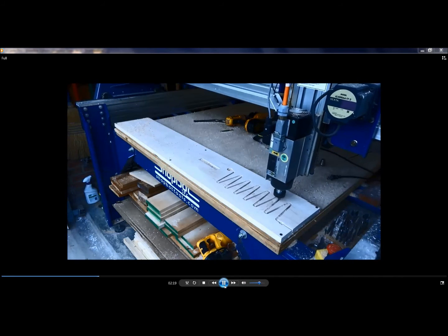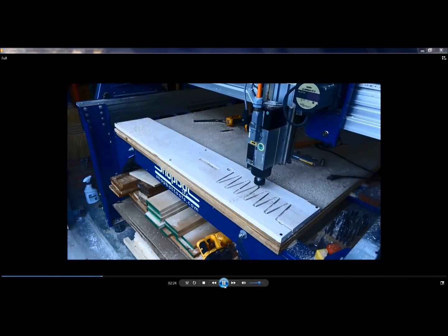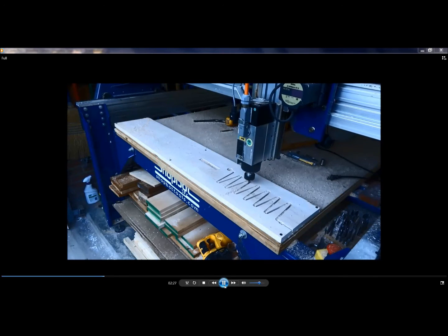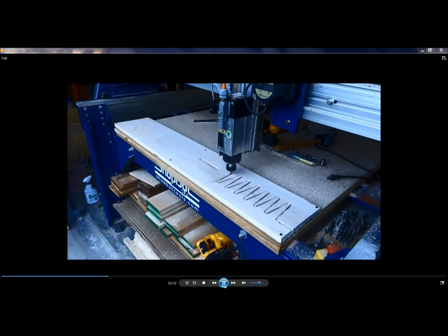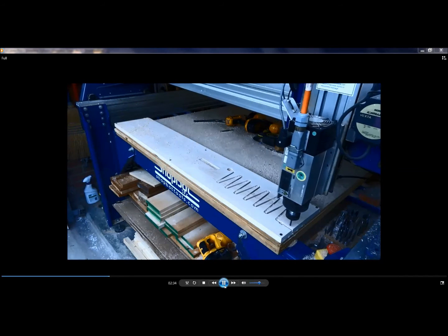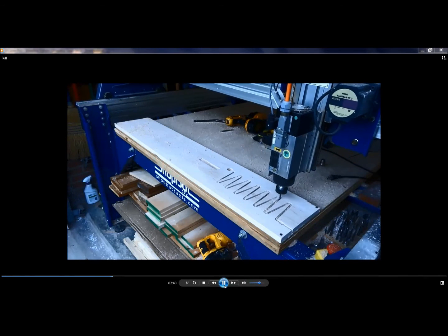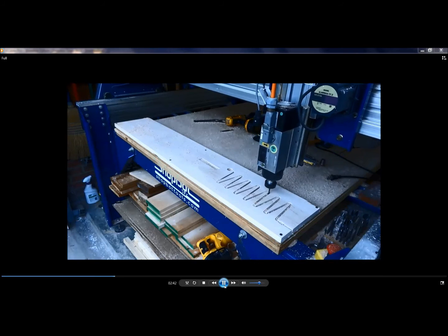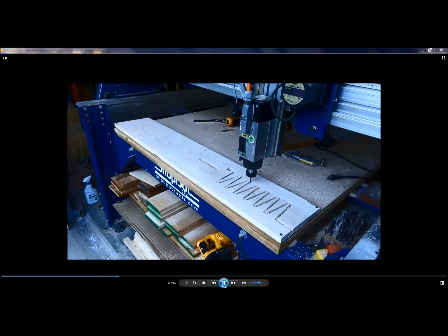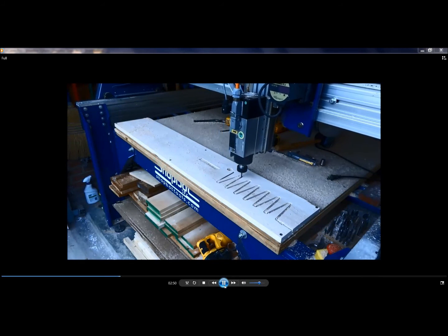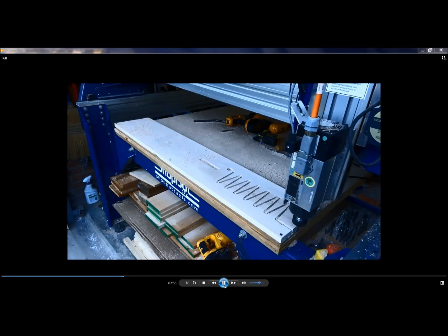And this would be really important for you to have an upcut bit to be pulling the chips out of here, have your dust collection going so these chips aren't going all over your shop and up in the sawdust in the air. But notice how it exits there in an area that's already been pocketed out. And same thing, it's starting over off the board. Wanted you to be able to see both examples. A lead in where it's off the material, which sometimes you'll want to do. And then the lead out, well, it's in the middle of the material, but I still need it to pick straight up. Well, that way I can put a pocket there and temporarily make it.